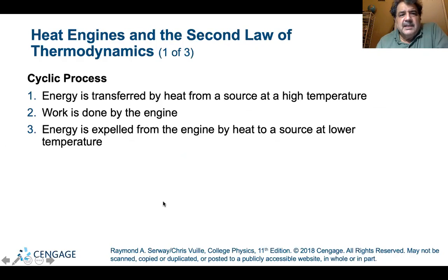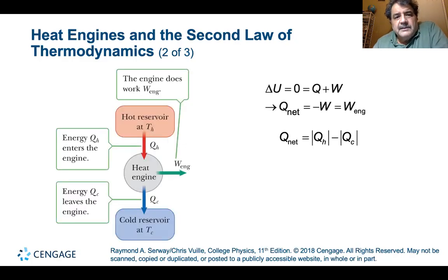Okay, let's see. Heat engines and the second law of thermodynamics. Cyclic processes. Energy is transferred by heat from a source at a high temperature. Work is done by the engine, and energy is expelled from the engine by heat to a source at lower temperature. So this is the heat engine. You have a hot reservoir at T hot. You have a cold reservoir at T cold. The engine does work. This is the work of the engine. Energy Q hot enters the engine. Energy Q cold leaves the engine.